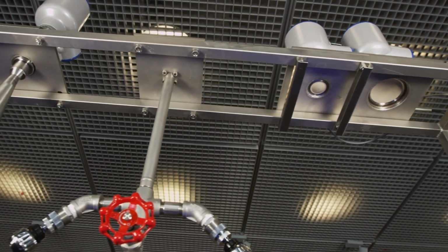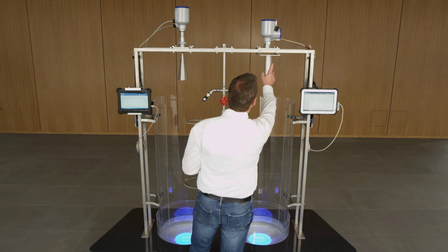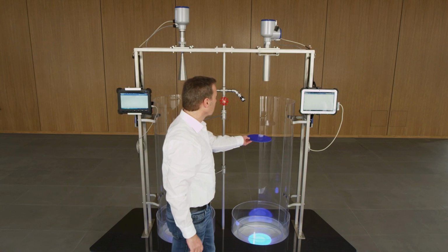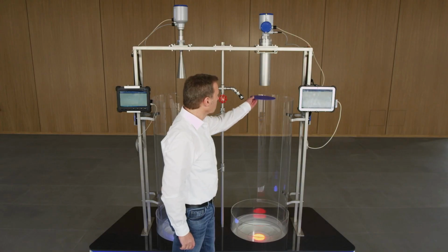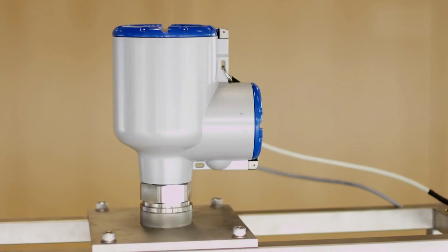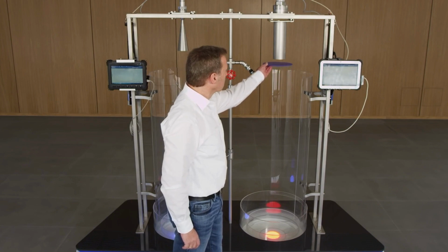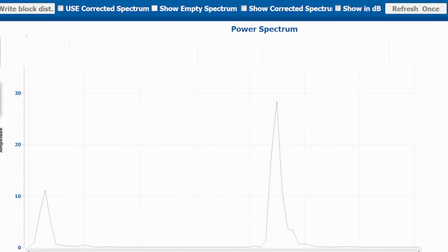Lens antennas, however, can be easily placed on nozzles, as shown in the example of a 50 mm nozzle in combination with the 40 mm lens antenna. A disturbance signal at the nozzle end, as is usual at 24 GHz, does not occur. Thus, filling is possible up to the lower edge of the nozzle. The combination of a 70 mm lens antenna with an 80 mm nozzle provides, of course, identically good results.